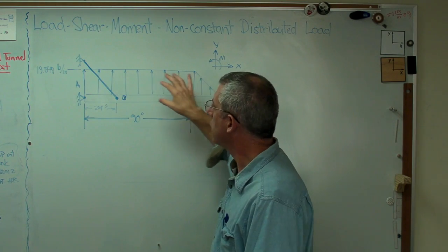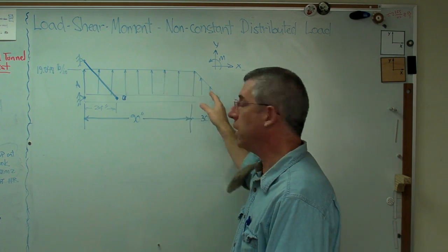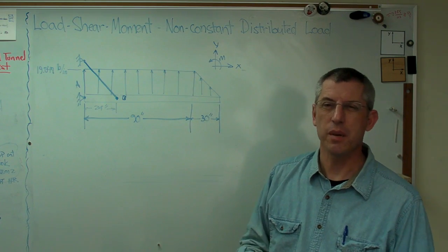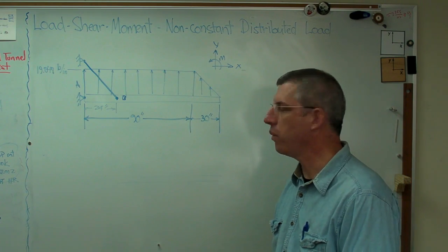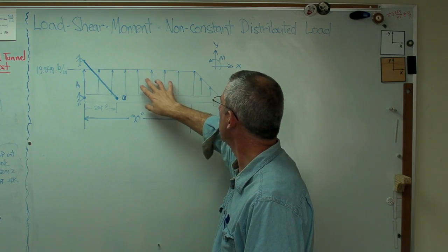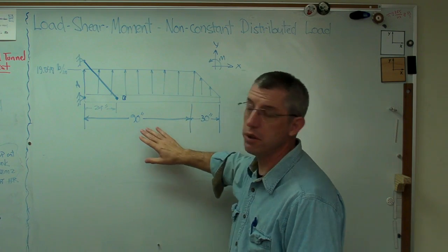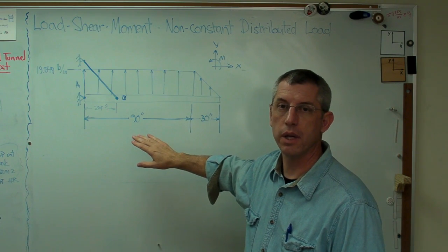Now, theory says, and in practice it's really true, the lift is approximately elliptical as you go down the wing. Well, an ellipse is kind of an awkward shape to work with for what we're doing here. So I thought I'd go ahead and break this down into a rectangle and a triangle. That's approximately an ellipse. Now, I've also done everything in English units.